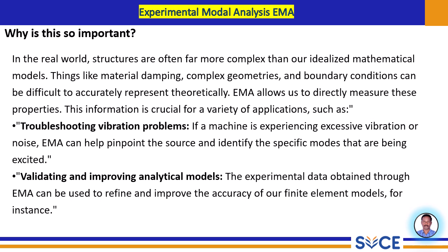Factors like inherent material damping, how quickly a material dissipates energy, can be notoriously difficult to model accurately. Similarly, complex geometries with intricate curves and varying thicknesses, and real-world boundary conditions, are not perfectly possible to capture in mathematical modeling.